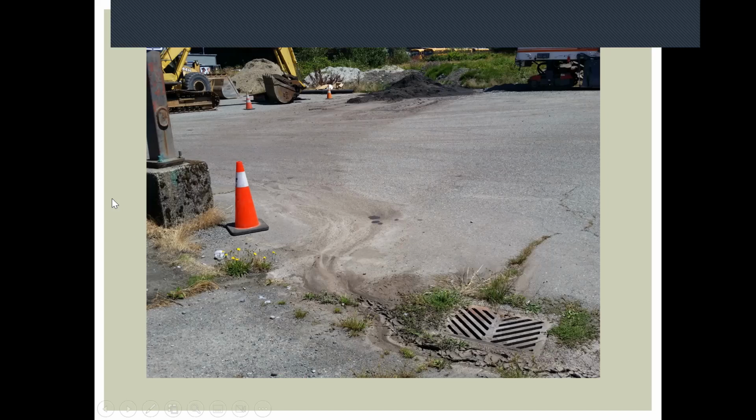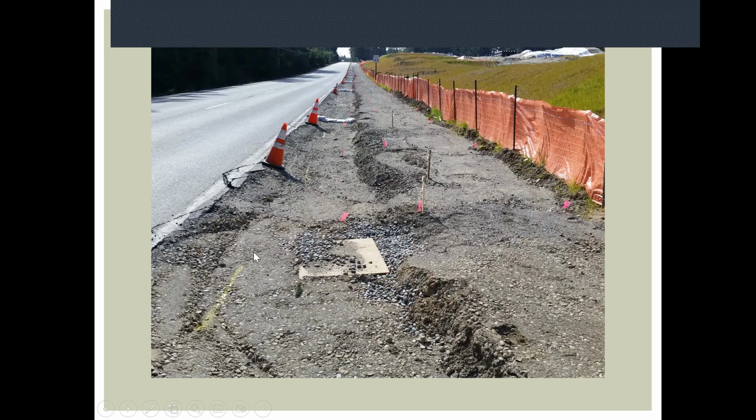So I'm going to focus again a lot on water and the effects of water on soil of any kind, and things to look for. So catch basin, you can see stuff's been draining into it. I'm not concerned that there's not a catch basin insert in there. There probably should be, but again, an insert's not going to do anything for turbidity. So you really want to prevent.